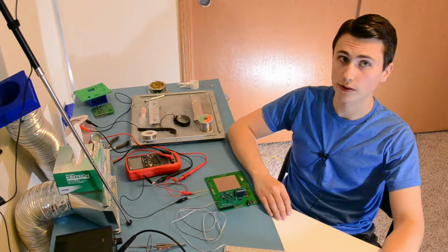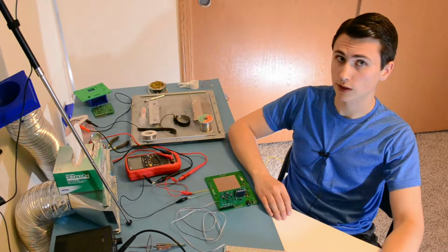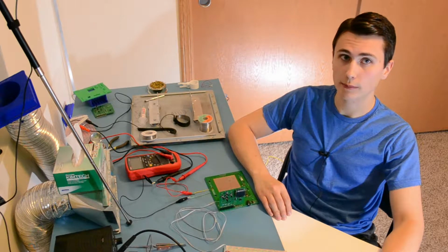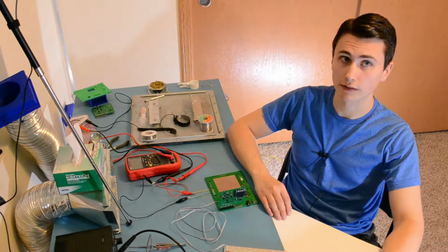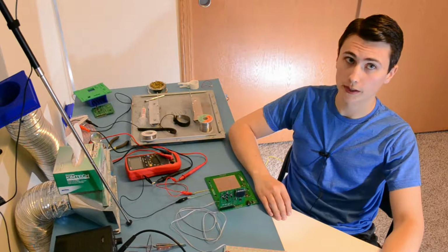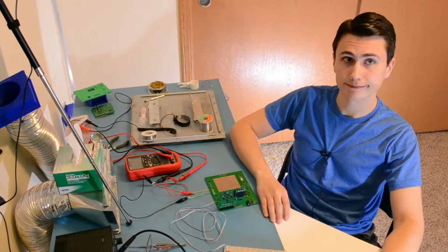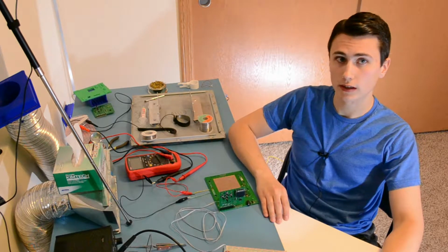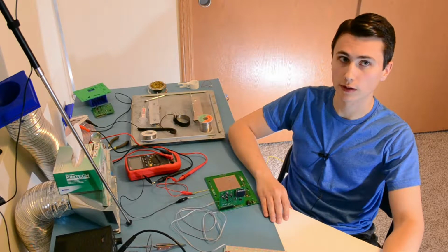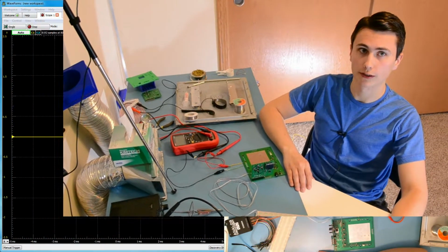Instead of talking about the theory of operation, we're going to measure the current regulation performance at a few set points as RMS and peak-to-peak values. We will run the lamp at a few different current set points and evaluate how close the current regulation of the LED channel is to what we would expect. In this case, we'll be evaluating the blue LED channel. 100% duty cycle from the microcontroller would result in 333 milliamps of current flowing through the LED channel. 0% would result in 0 milliamps of current.